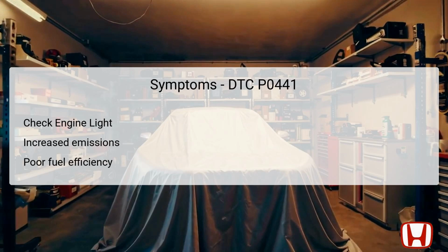Additionally, an impaired EVAP system can cause the engine to run inefficiently, which may be reflected in lower fuel economy. Drivers might also experience an unusual smell of fuel when the system is not sealing properly. Taking immediate action on these symptoms is important to avoid further damage and ensure compliance with environmental regulations.